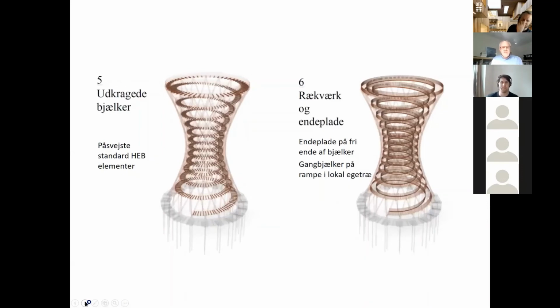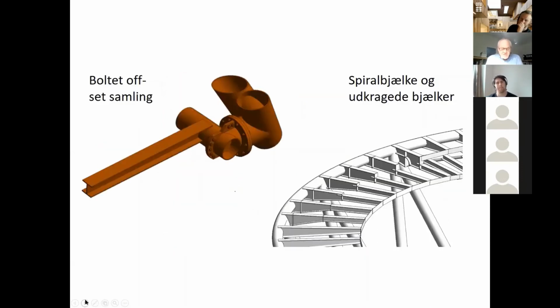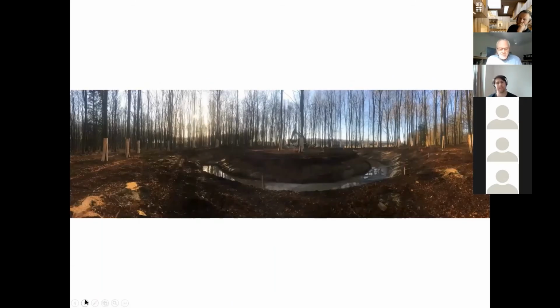The foundation consists of the foundation piles and a concrete ring beam on top of the piles placed below the ground surface. On top of the ring beam are placed 18 concrete supports, concrete cones with the top over the ground surface. The foundation as such did not give us any special challenges apart from a bit of strong pile driving.